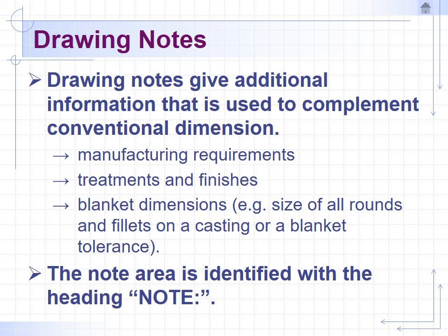So the last little thing here is notes. You will come into notes, and generally some of the most important things that you want your reader to appreciate are put up in notes, and often quite bold, and usually with a big label on it, note. And sometimes I put in my reference standards here too. They talk about manufacturing requirements, but for me as a civil engineer, manufacturing requirements might be, all work shall comply with the current building code, something like that.